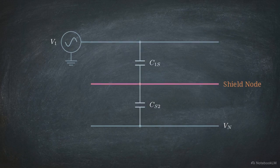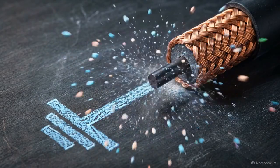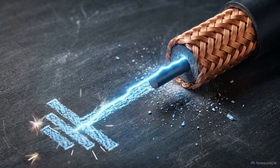The circuit behavior is consistent. The shield re-radiates that exact voltage to the inner conductor, resulting in a noise voltage equal to the shield voltage itself. The ungrounded shield accomplished absolutely nothing to protect the circuit. It just passed the noise right through. The mathematical solution, then, is to actively ground the shield. By establishing a low-impedance connection to the chassis, you force the shield voltage to 0 volts. With the shield held at 0, the first capacitor is completely decoupled from the second, entirely breaking the noise channel.